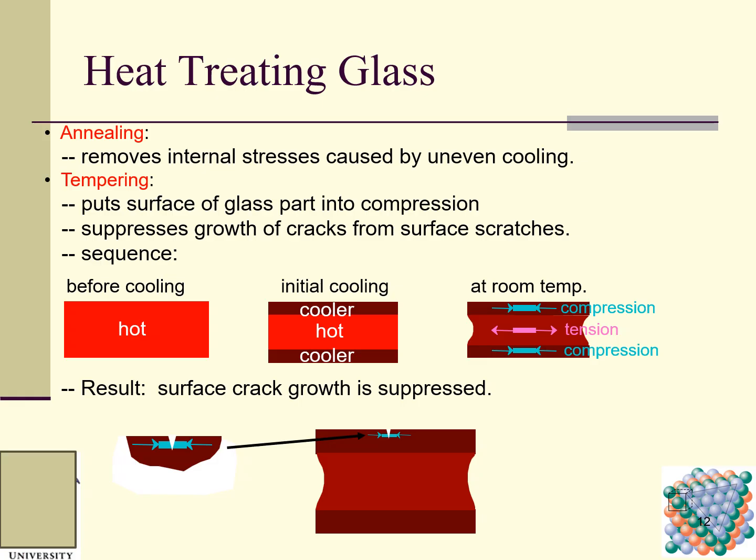After some time, the samples in the chamber will be hardened on the surface, and at the same time we will have a beneficial compressive residual stress on the surface to enhance the fatigue life of the specimen.